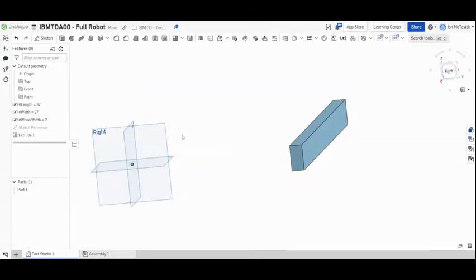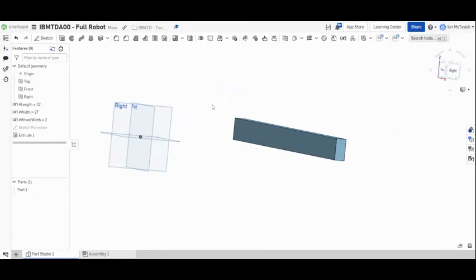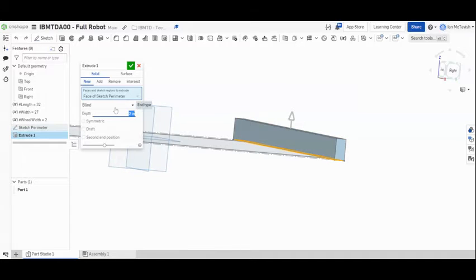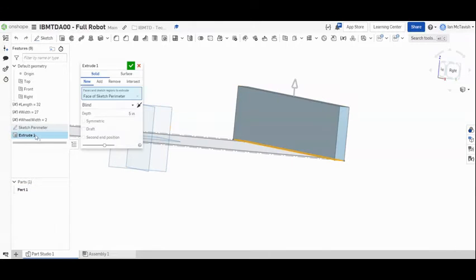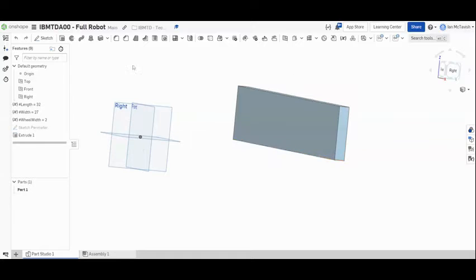And if I click that, you can see I now have a part, and down here where there's parts, there's my part that I've just created. And I can turn the eye feature on and off, so I can hide it if I don't want to see it. I can click the eye to make it visible again. And that's the part. If I modified that extrude, change the dimensions, you can see it automatically modifies. And that's really powerful. If I changed my sketch, it would automatically change.